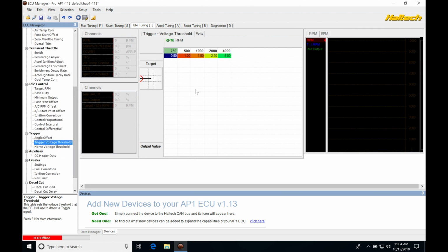So it's essential that we have some kind of a voltage here, or again, we could pick up extra teeth, and the Haltech may go and not know what to do and have misfiring because it can't calculate the proper ignition timing and where to spray the injectors and on and on and on. So I usually leave these tables alone.